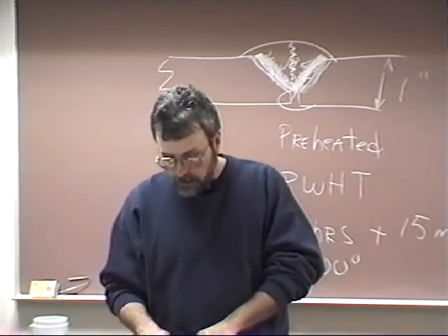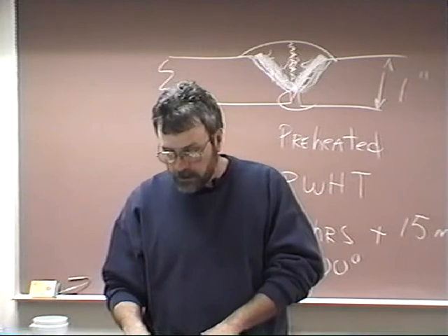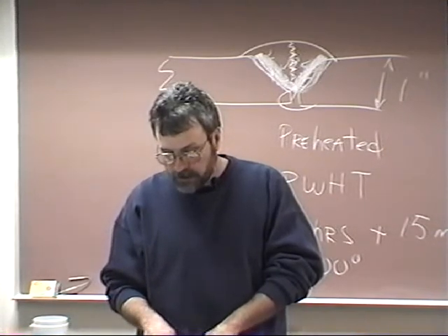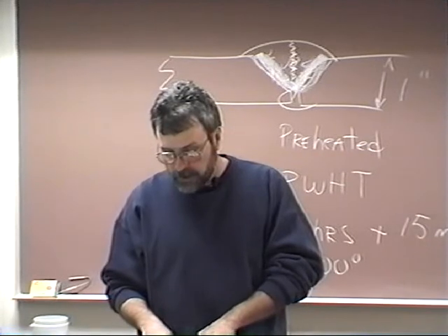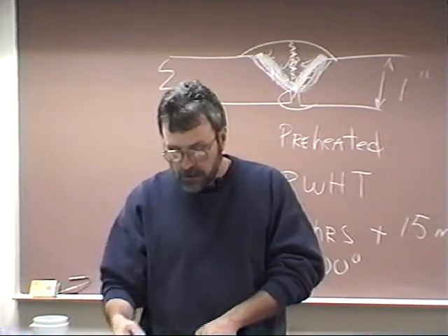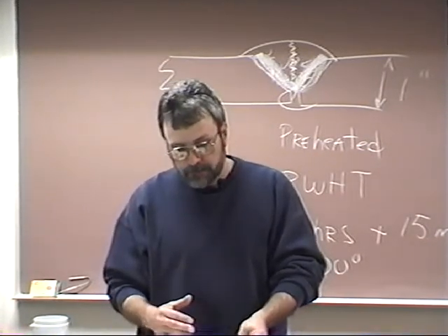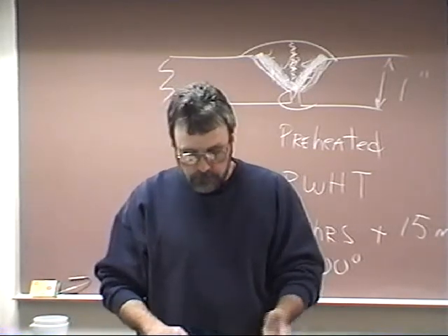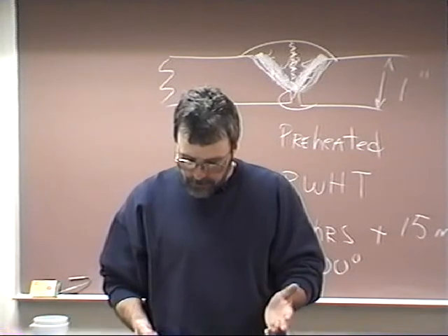Second step, okay, if a welding procedure already exists for the weld being made, then it should be reviewed in terms of the following: the type of material, the electrodes, the joint preparation, interpass temperature, and preheating temperature, and you will use the same procedure to make your repair. So how are you going to make that repair?